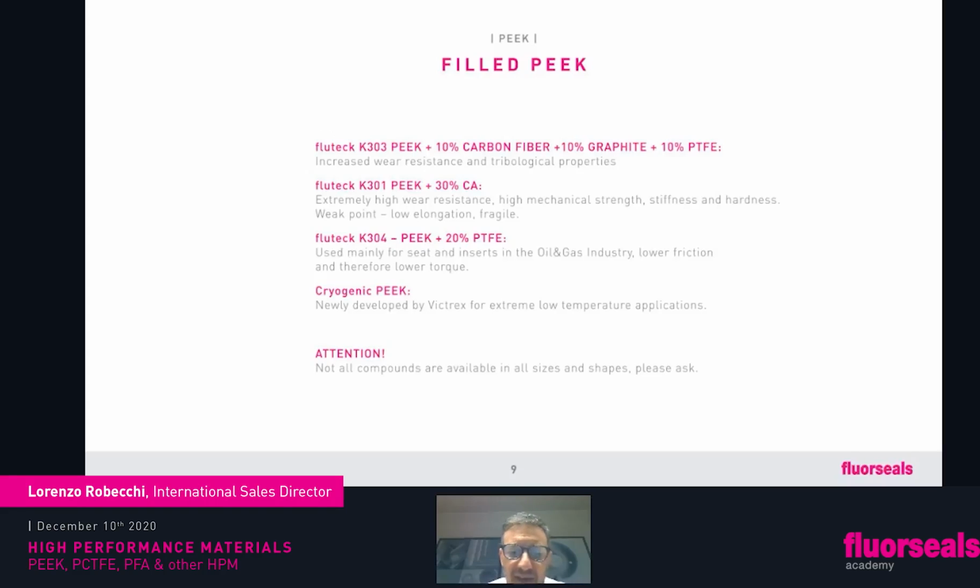Like many other plastics, PEEK can be filled. We have a few examples here. Not so many fillers are available for PEEK as for other plastics, for sure not as many as for PTFE. One of the most common is what we call the K303, which is 10% carbon fiber, 10% graphite, and 10% PTFE. It's a typical tribological application. So carbon fiber gives more wear resistance, graphite and PTFE help to lower friction. Typical material for sealing application.